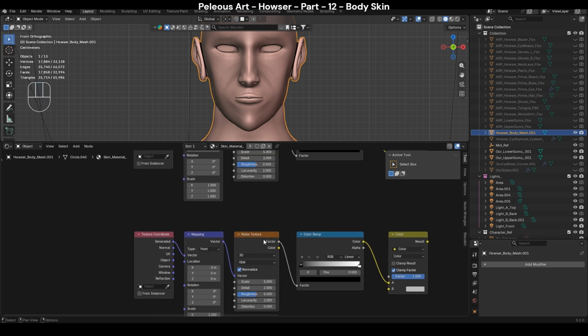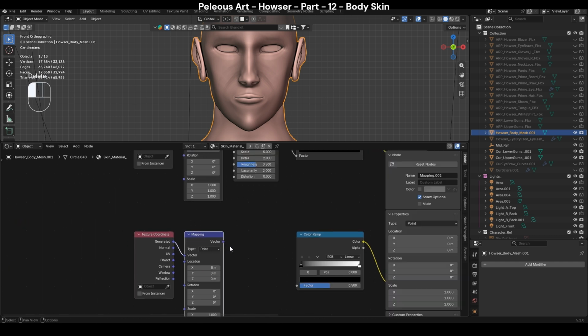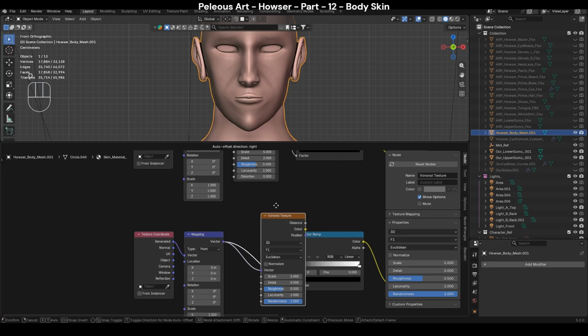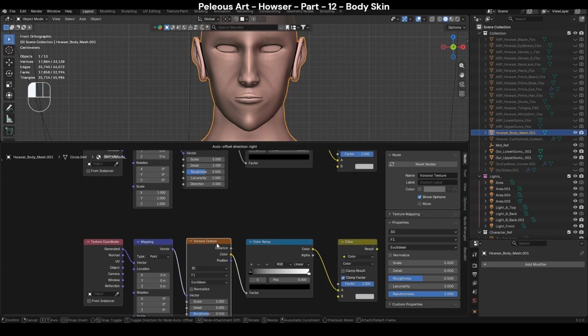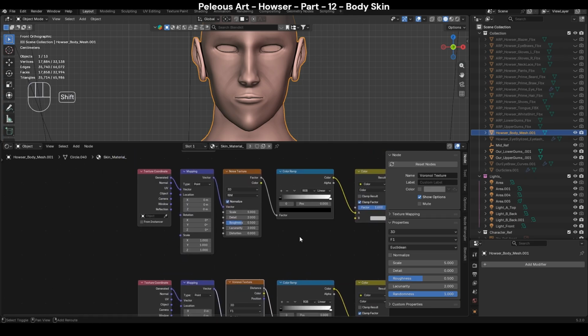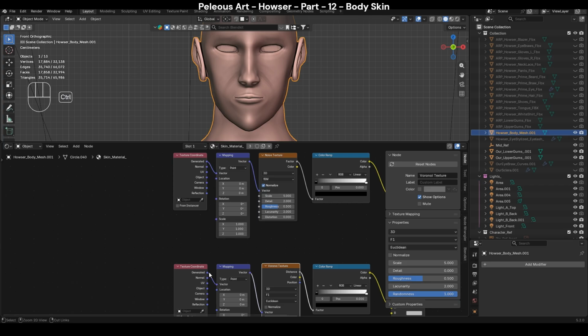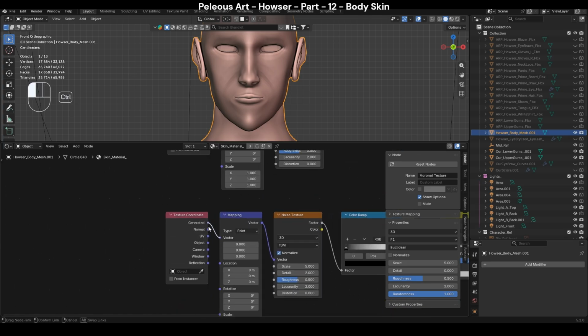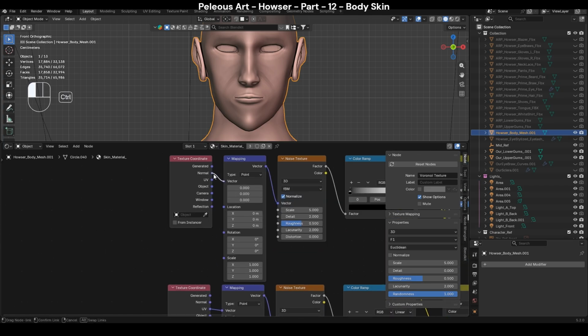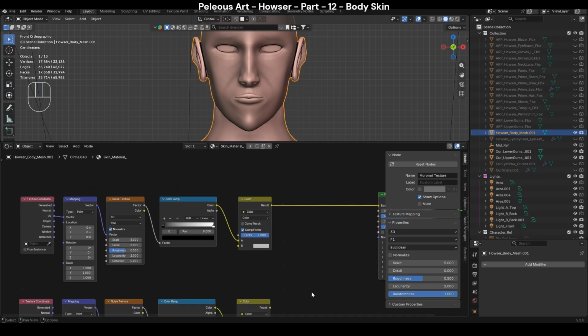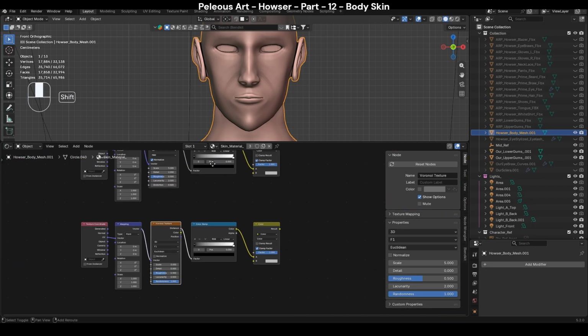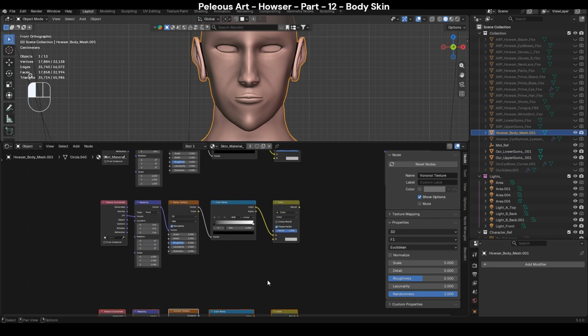Let's separate the noise texture with Alt, put it aside, connect the vector to vector, then we can click and drag and get ourselves a Voronoi texture. Place it right here and connect it into distance. Let's switch from generated to UV in all of them. You can move it with Control. Okay, and now we can place the masks in between.